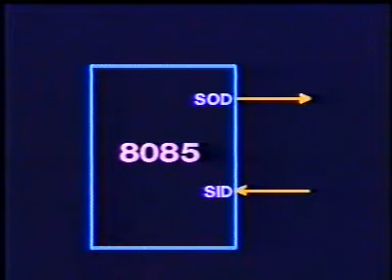When the RIM instruction is executed once, the single bit data available at the SID pin is brought into the accumulator as the D7th bit. All other bits are made 0. Thus, the SID and SOD pins may be used to transmit data in and out of the microcomputer. The framing of the data for synchronous or asynchronous format can be done using software. A better approach is to use a dedicated device to handle the serial communication.